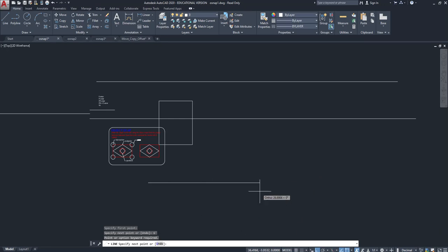And AutoCAD's not really doing anything. 6 foot, enter. I don't get an error that says, hey, I don't recognize these units. Nothing happens, right? So I get emails from beginning students and they're like, I'm trying to input this and my line is just not working. I hit 6 foot, I hit enter and nothing happens, right?